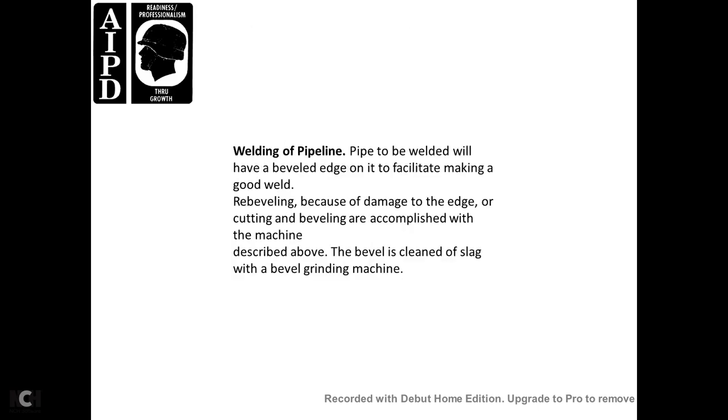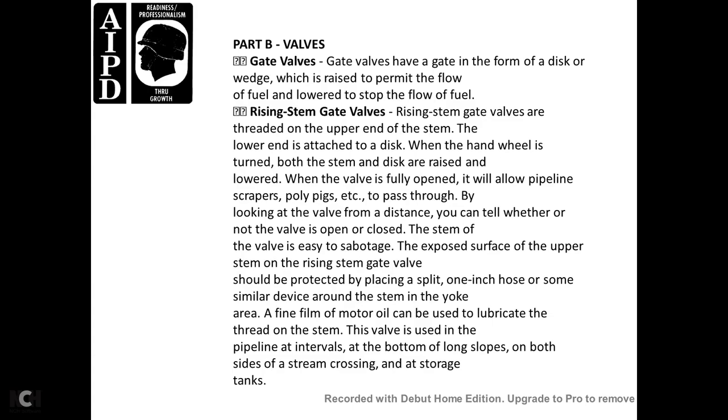Welding a pipeline. Pipe to be welded must have a beveled edge to make a good weld, and must be rebeveled because of damage to the edge. The cutting and beveling are accomplished with the machine described above. The bevel is cleaned of slag with the bevel grinding machine.